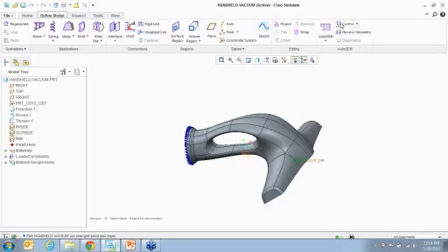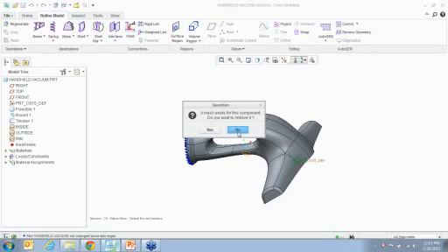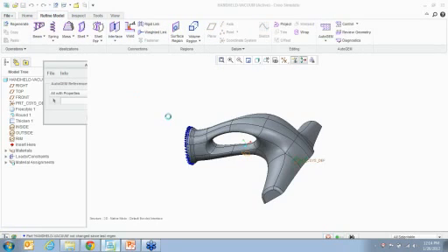So right now I'm going to try and create a mesh in here. So let's go say AutoGEM, and let's go create a mesh. Now you can see it's going to be a little while before it creates a mesh. The reason being it's extremely thin, and we're trying to create solid elements. I ran this before. It created about 10,000 elements for me when I did this. So it's just going to be a couple of seconds while I do that.